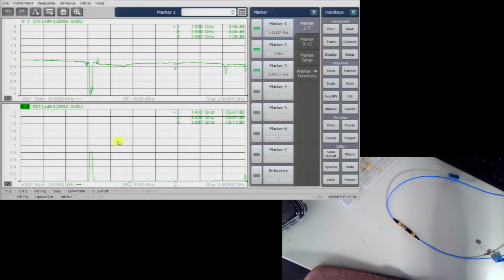All right, so what is our pass frequency, our center frequency? Well, let's spin the knob for marker 1 and put this back up at the top again. We can look at the reading and get our maximum. Looks to be about minus 1.7. So we would determine the bandwidth by finding the 3 dB points, which would be minus 4.7 on either side.